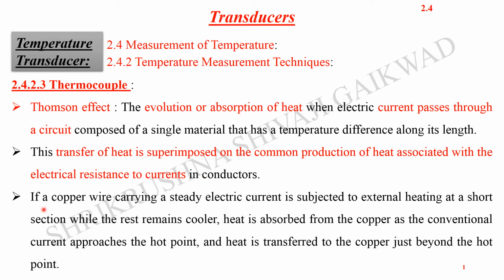Suppose we consider a copper wire which is carrying a steady electric current and is subjected to external heating at a short section, while the remaining region stays cool. Heat is absorbed from the copper as the conventional current approaches the hot point, and the heat is transferred to the copper just beyond the hot point.